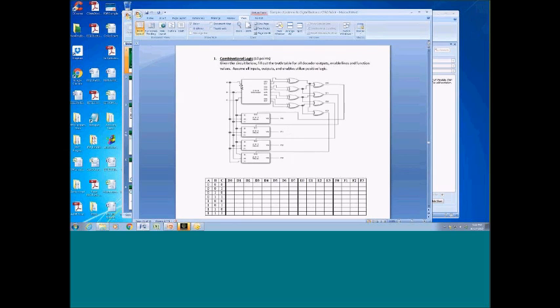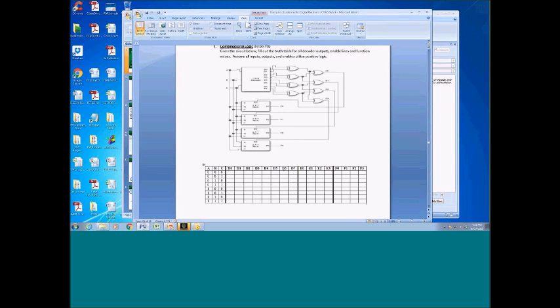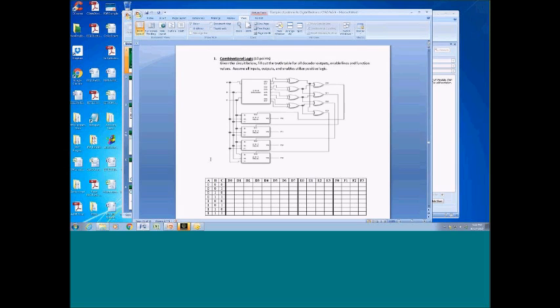Anyway, it's a 3x8 decoder, of which I took each of these minterms and put them in these XORs and did all these kinds of functions. I fed these things back into the enable of multiplexers, and then I had F-Zero come on, and I did want them to draw this truth table out. The idea was for them to work through it piece by piece to figure out what was going on, and then of course all these became the inputs for the muxes as well. So I was very proud of myself for putting this together. Didn't mean it was a good idea.